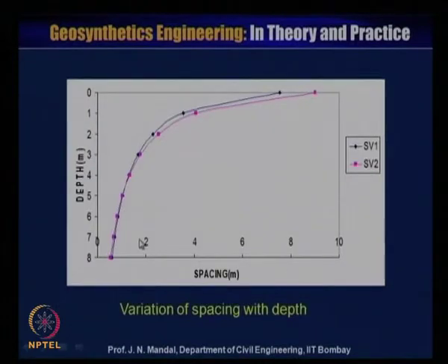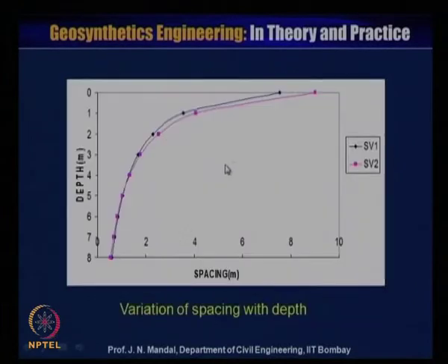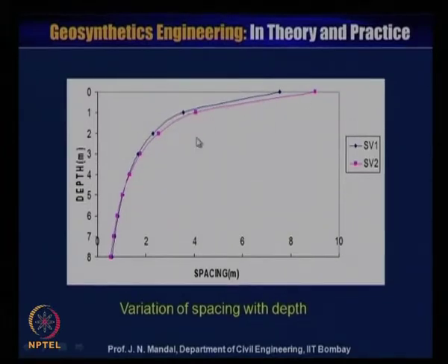Here also, between the spacing and the depth for the defined values of SB1 and SB2, I have shown the curve with depth. You can see that as the depth is increasing, the spacing is also increasing, and after a certain point it is like this. So, whatever it may be, you have to consider a spacing of about 1 meter or less.